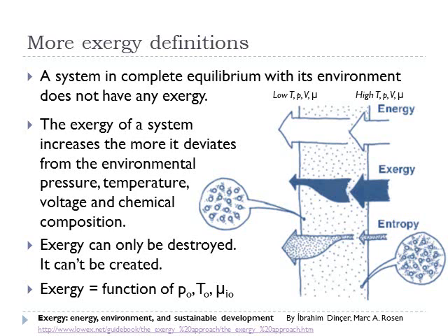The exergy is high on the high temperature side, and when it gets over to the other side, what you're left with is maybe much smaller. So exergy is decreasing, but what's increasing is the entropy associated with that thermal energy. The entropy for the same amount of energy is low on the right side and high on the left side.